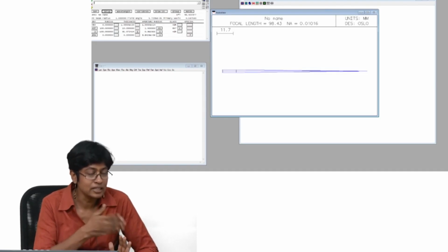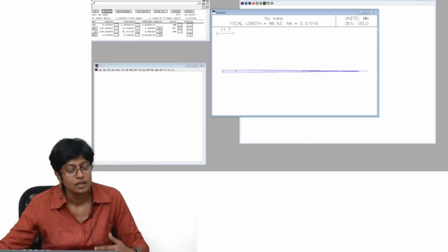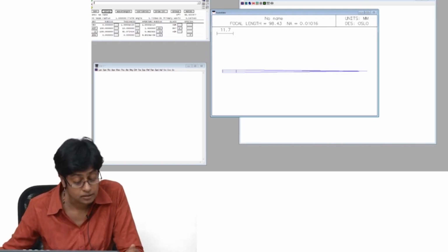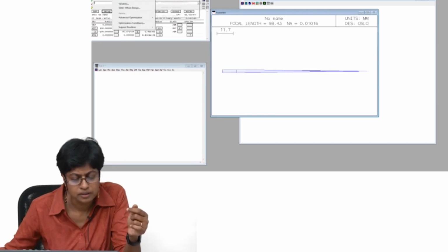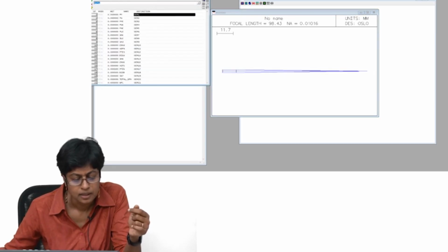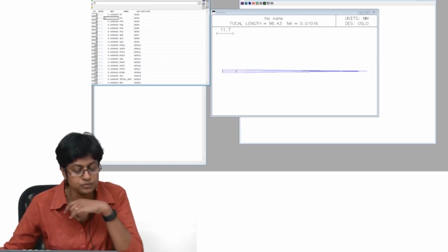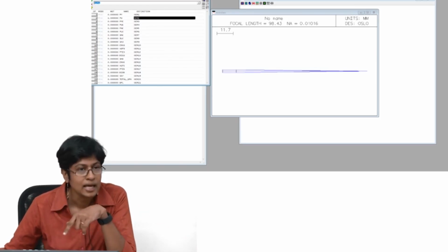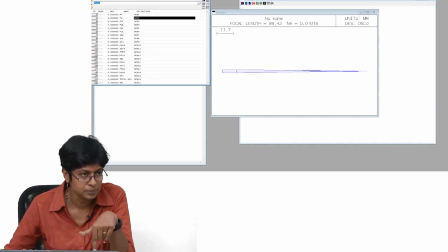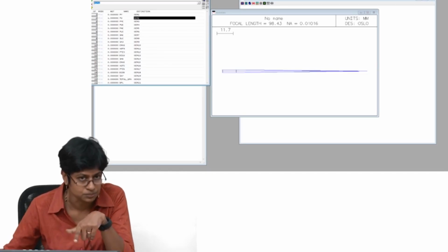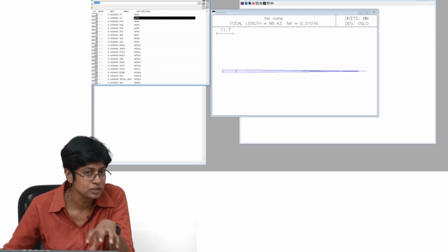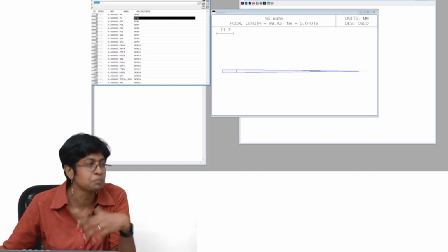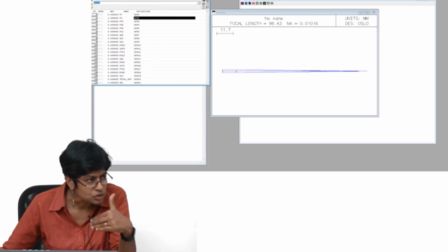It's the axial ray. I can define it at any interface. We went to generate error functions, aberration operands. We wanted PU, so we changed the weight of this to 1, and then if you choose some parameter as a variable, OSLO will try to minimize this to 0. Here we didn't want the angle to be 0, we wanted the angle to have a certain value. So you add or subtract whatever needs to be, so that the total sum goes to 0. So you are controlling the angle.